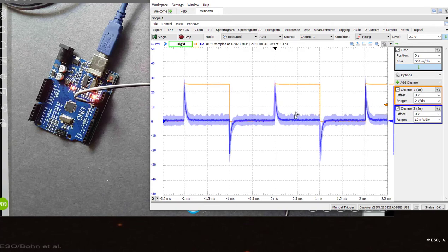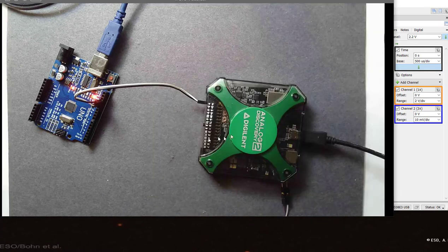Where is that noise coming from? I mean, there's absolutely nothing connected to channel 2. Because it is a high impedance input, that tells us it's going to be capacitively coupled from the aggressor. It's coming from the capacitance on the circuit board between the channel 1 traces on the board and channel 2 traces on the board before they get into the amplifier. It might also be happening inside the amplifier itself. There may be some crosstalk there. Can't separate it from this measurement, but it's all about the intrinsic coupling in the 82.